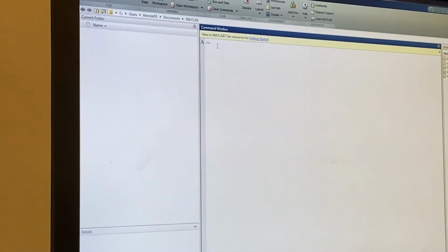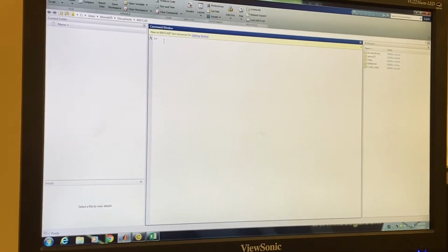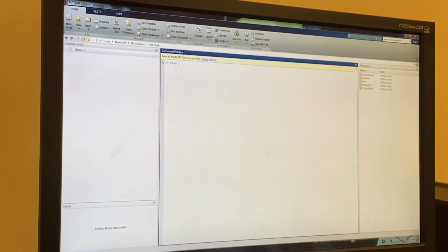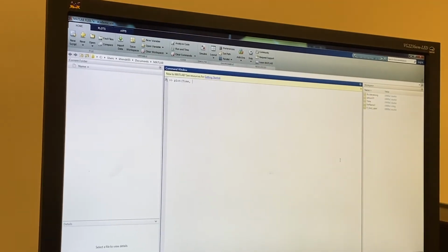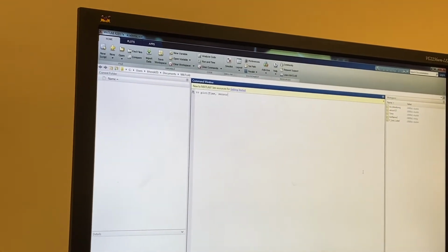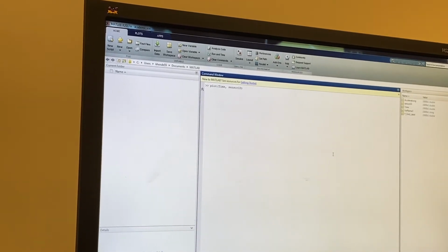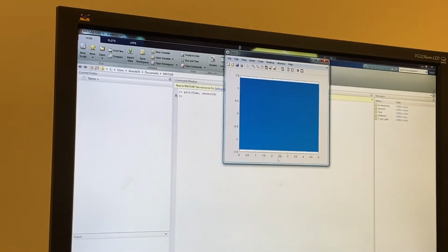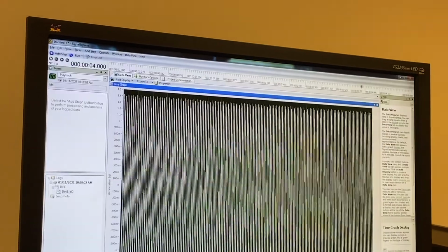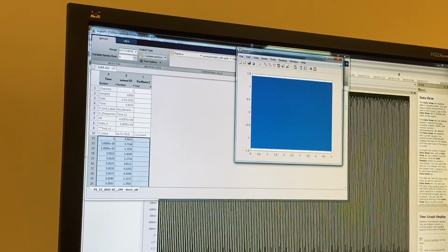Now if you have these two variables, how will you plot them? Go over here, plot, time versus sensor 1D. Maybe you can just plot it to see what we get. You see the data is there. The same thing which you saw in our LabVIEW Signal Express has been transferred into Excel, into MATLAB.